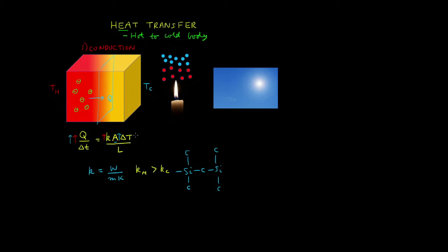And now the next quantity is the change in temperature, which is equal to the difference between the hotter and the colder temperature. And delta T on L can also be looked at as a temperature gradient, which is a change in temperature over the thickness of the material where the heat has to travel. So this will be the L dimension. So that also makes sense that if we have a higher temperature gradient of delta T on L, then we have a higher rate of heat transfer.